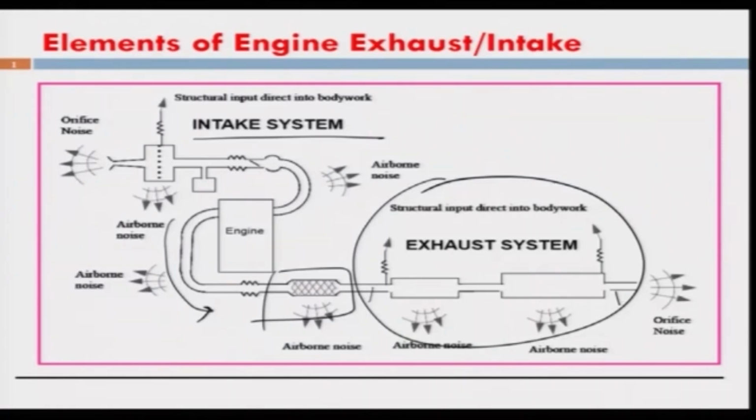We see here muffler 1, muffler 2. It is not very sacred, you can have very different arrangements. You can have double outlet mufflers also, which is popular. Basically, these are the elements that constitute the muffler. You see an inlet port through which air comes or the acoustic power is incident, and some part is reflected back, some part is transmitted, again some part is reflected back, some part is transmitted, and this process is repeated for muffler 2. And eventually very little acoustic power is transmitted into the atmosphere, at least for the frequency range of interest. That is how you design a good muffler.